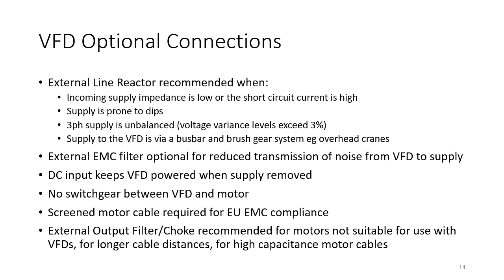An EMC filter is also optional. That reduces the transmission of noise back from the VFD to the supply. The reason for that is, we've got these complicated power electronics running at high frequencies, and they create harmonics. Some of those harmonics could be fed back into the supply, so having that external EMC filter can minimize the amount of those harmonics and the transmission of that noise.